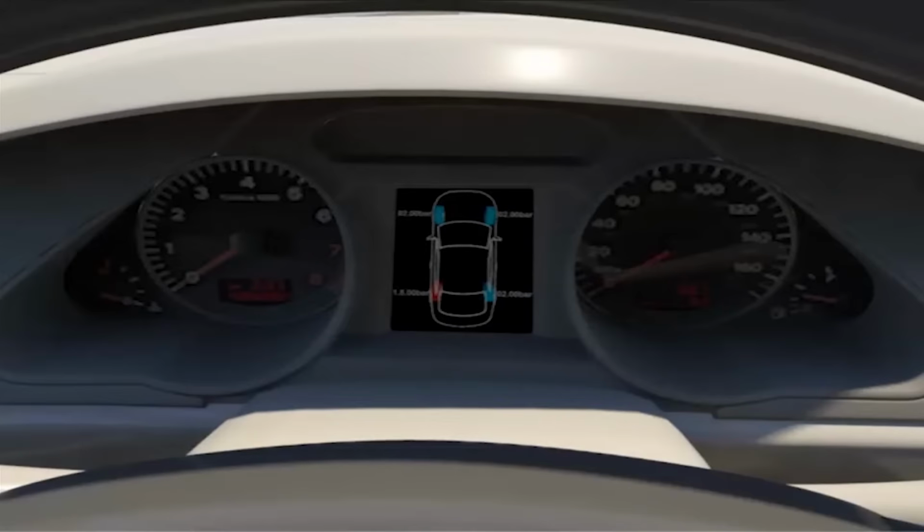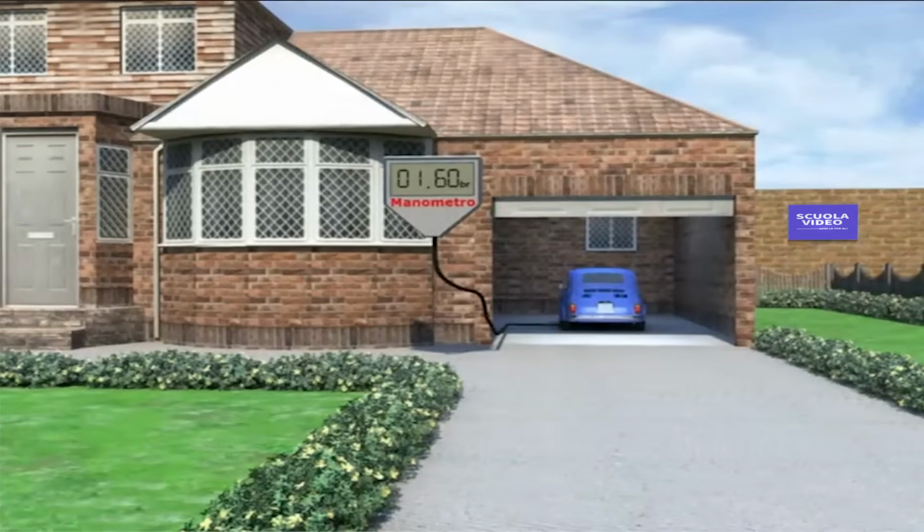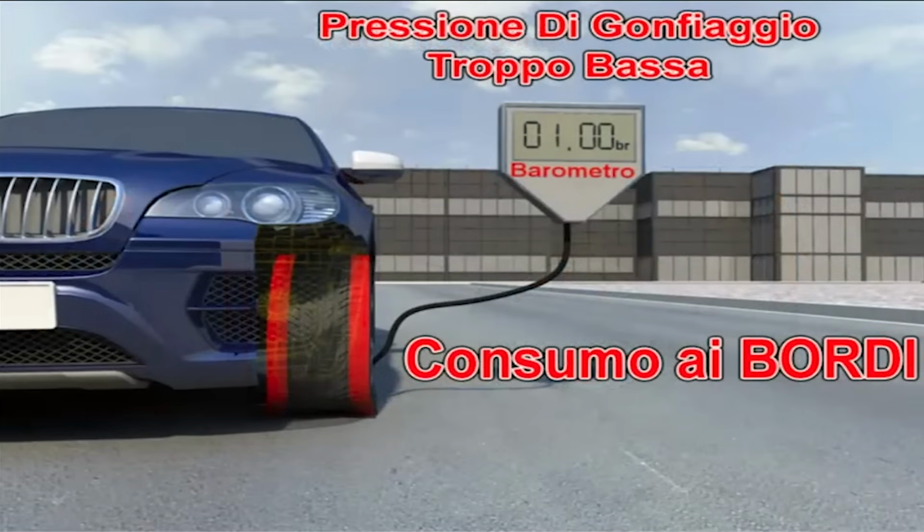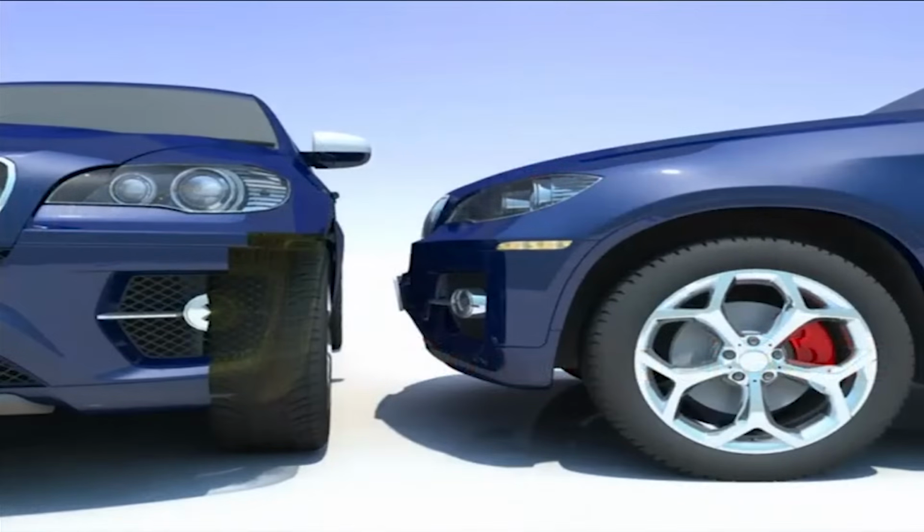Tire inflation pressure can be detected by an automatic detection system, which increases safety for vehicles that are equipped with them. On the other hand, for vehicles not equipped with this system, the pressure must be checked when the tire is cold in order not to have a false detection by the temperature, since insufficient tire inflation pressure increases friction and also fuel consumption. It causes abnormal wear at the edges and compromises stability, especially when cornering.